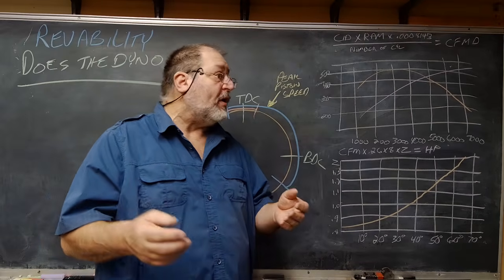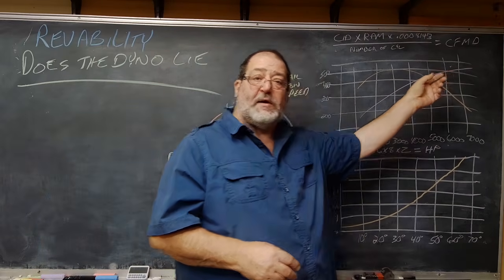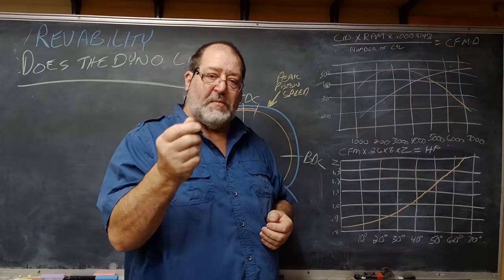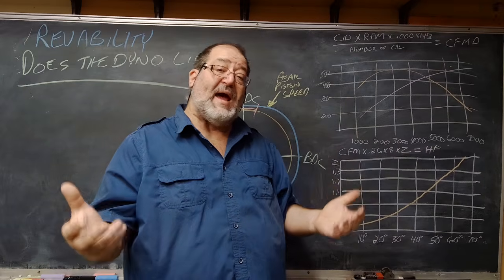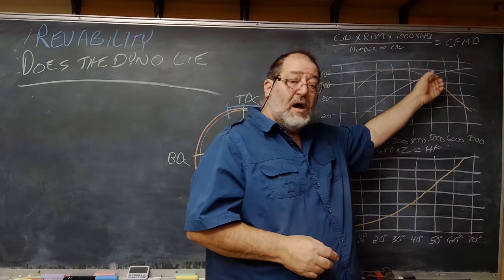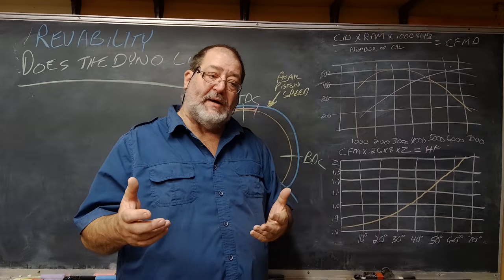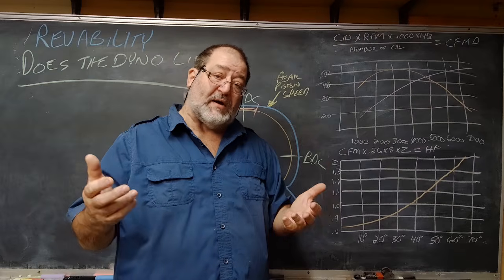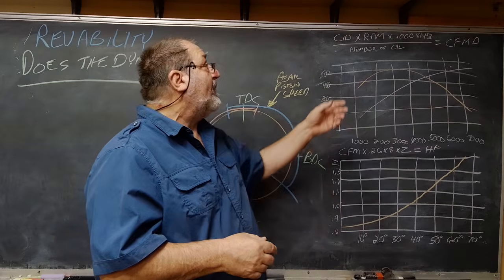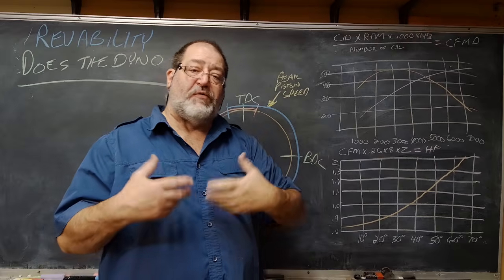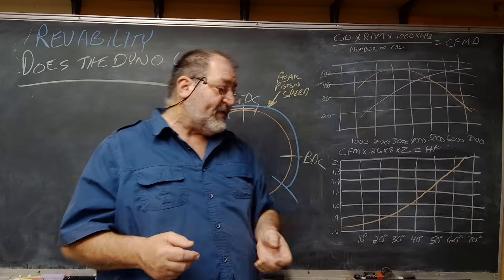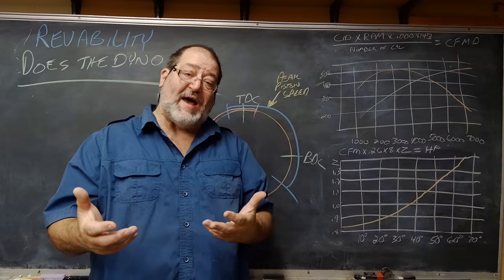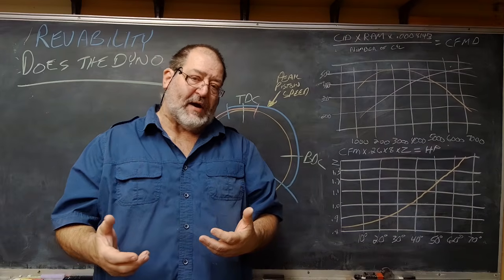Now, a big port will help you up here. It sounds better. You can get that carryover, you can get that power up there, the motor sounds clean, because you've got a big head, and by the time you get up there, the airspeed's okay, and you have fairly decent breathing. If you have extra breathing, more than what you need by the CFM demand formula for the RPM you're working in, well then you can get away with less cam, and the motor tends to rev better. That revability is there.